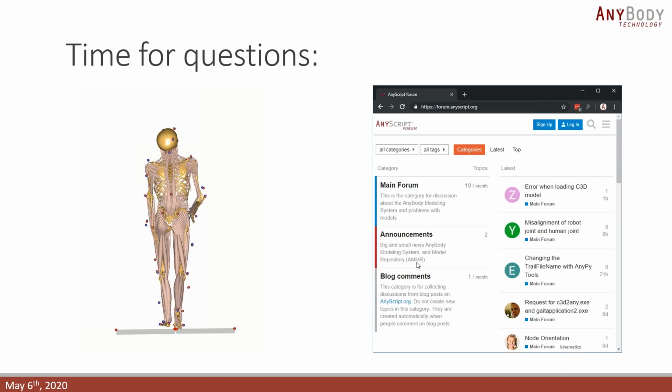Another question we got was about the muscles you modeled. Were the muscles modeled as simple muscles or 3D Hill models? They were modeled as three element Hill type models. Okay, and how were these muscles calibrated? Is it some kind of customized calibration or the default calibration? It was the default calibration, and we used the mass to solve the muscle requirement problem. We used this cubic polynomial function.